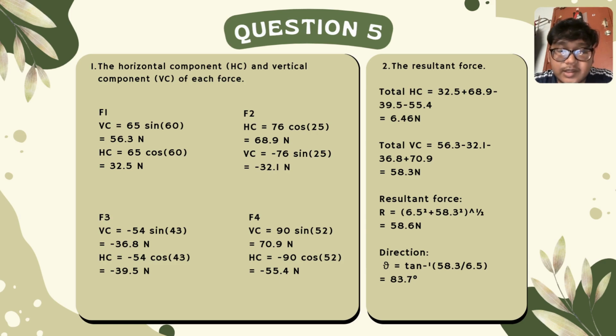The resultant force we get is 58.6 Newton. The direction is theta equal to tan inverse of 58.3 over 6.5, and we get 83.7 degrees in the first quadrant.